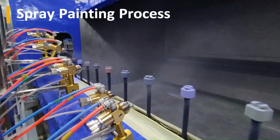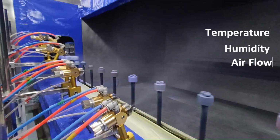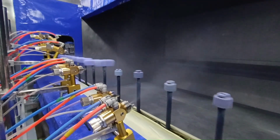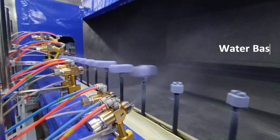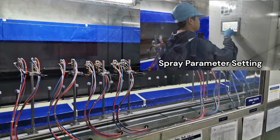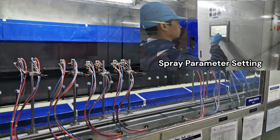Products will be sprayed under a controlled environment. Temperature, humidity, and air flow are controlled and monitored. Every spray booth consists of 2 separate spray guns for water-based and solvent-based paint. Spray parameters, air flow, water curtain, spindle rotation, and conveyor speed are set and controlled by the PLC system.